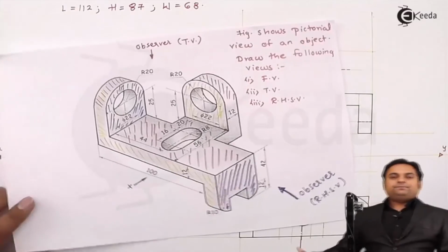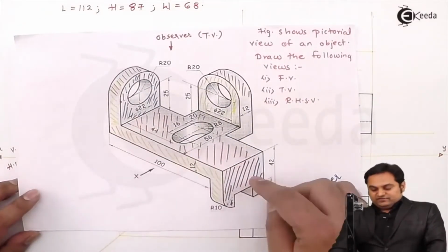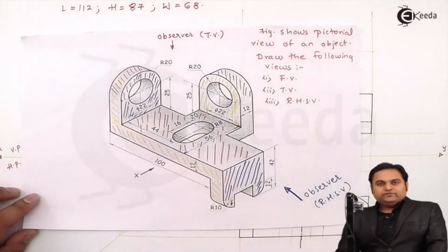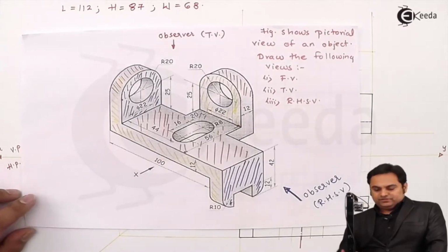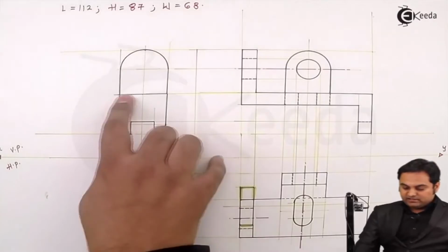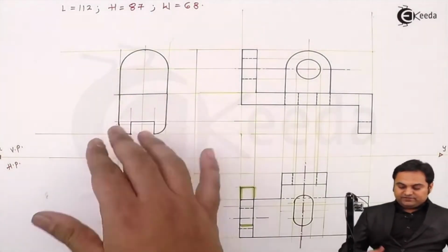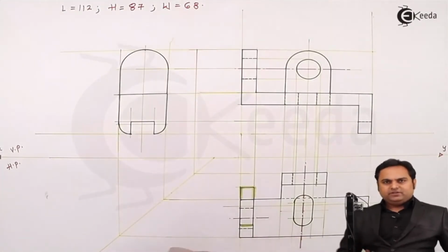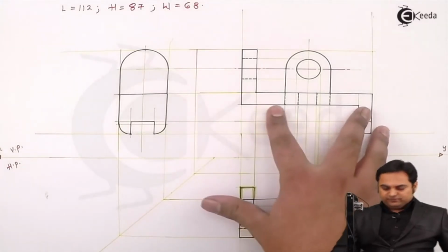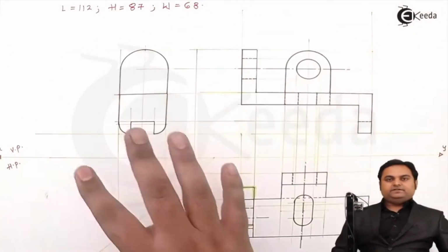As we see here, from the side view, both these surfaces which I have shaded blue are on different planes. So between them, there should be a dark line. Here, as we see, there is a dark line in between them, showing the change of plane. Which surface is ahead and which is behind, we can see from the front view: the bottom plate is ahead, the semicircular plate is behind.